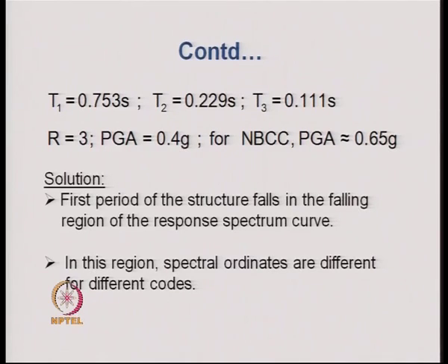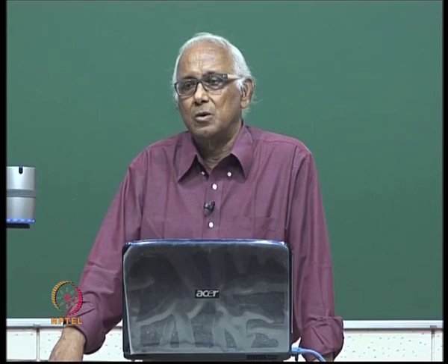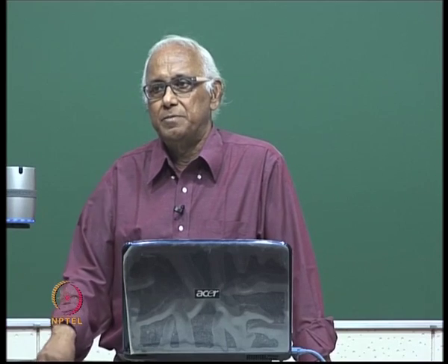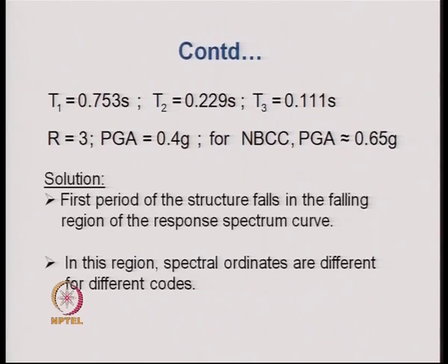For NBCC, the normalization comes out to provide an equivalent PGA of 0.65 g rather than 0.4 g. So, that is coming because of the normalization effect.